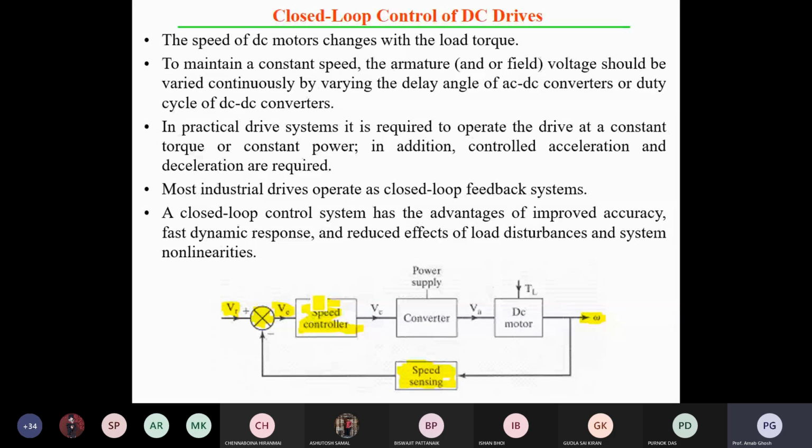So in the case of a PI controller, we are using the integral action. Okay, so what is the concept of the integral? It can minimize the error. By integrating that portion, you try to overcome the steady state error. That's why we are using integral. But the main problem is that the integral response is quite slow. But you know that the motor's mechanical time constant is much more than the electrical time constant. So there you can use the PI controller.